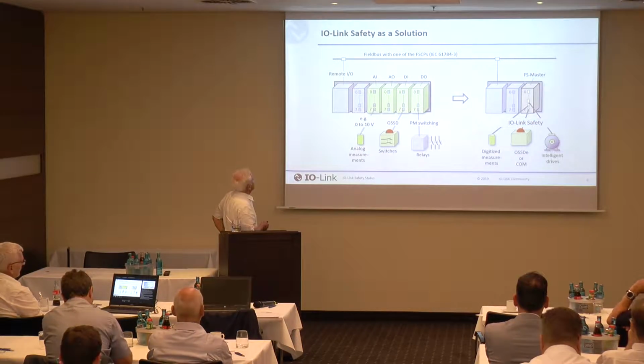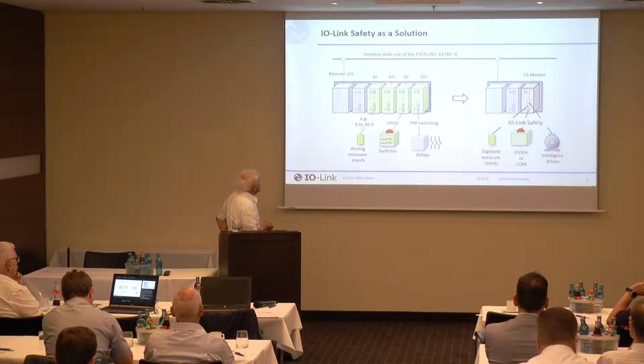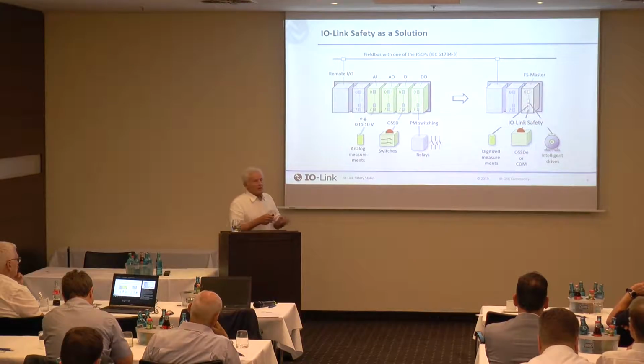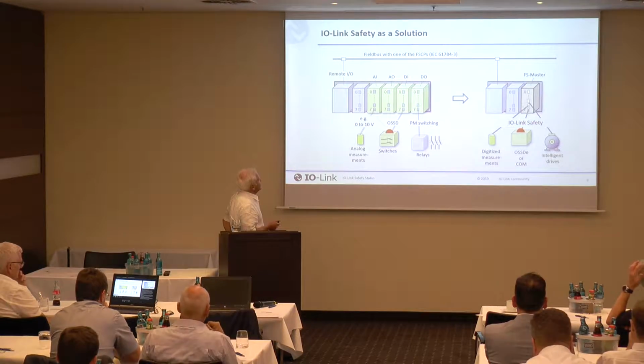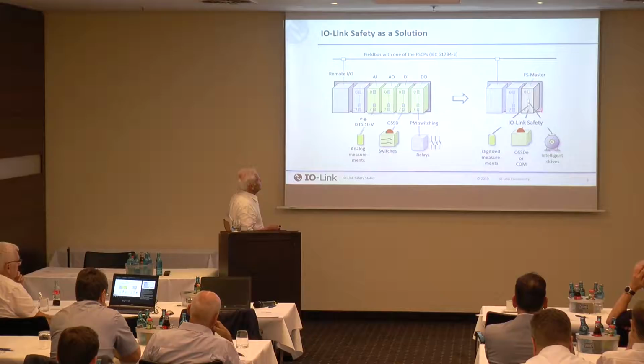Now our solution. Here you have this situation with the remote IOs. These interfaces are standardized. However, for analog input you need modules, for analog output you need modules, for digital input, digital output. So a lot of inventory you have to present to your customers. In case of IO-Link safety, we have only one functional safety master. It runs IO-Link safety, and you can connect whatever you want.